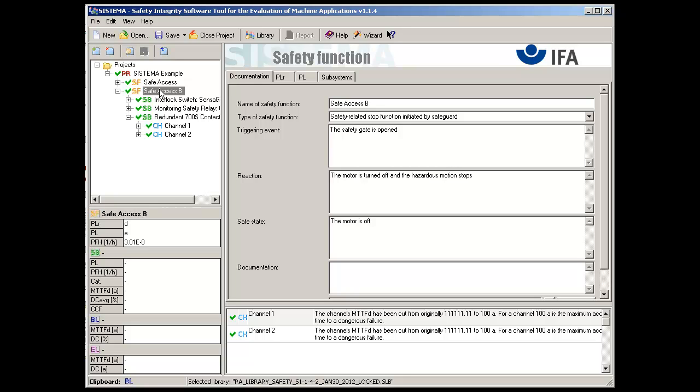As you can see, the use of electronic safety devices that do their own diagnostics significantly simplifies proof of conformance as compared to using electromechanical safety devices. This is driven by the 13849 standard itself, and, by extension, SISTEMA also reflects this increased complexity. This difference is a result of the fact that intelligent safety devices have these requirements already designed into them, thus reducing engineering effort required of the machine builder safety circuit designer.